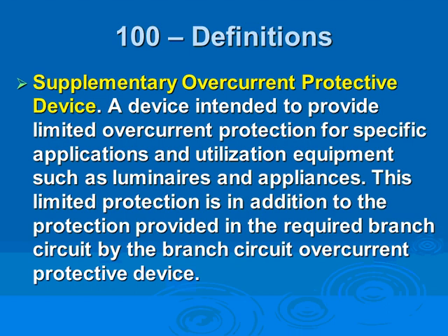Supplementary overcurrent protection devices, these are up to you guys. So you go to your VFD, and the manufacturer might stick a couple of fuses inside the VFD to protect their equipment. These are above and beyond the branch circuit overcurrent protection device, the feeder and the service overcurrent protection device. This supplementary protection is in addition to the protection provided with the required branch circuit. So certain equipment manufacturers say we are not going to depend on that. A good example of this is chillers, any chillers or condensing units and so forth.